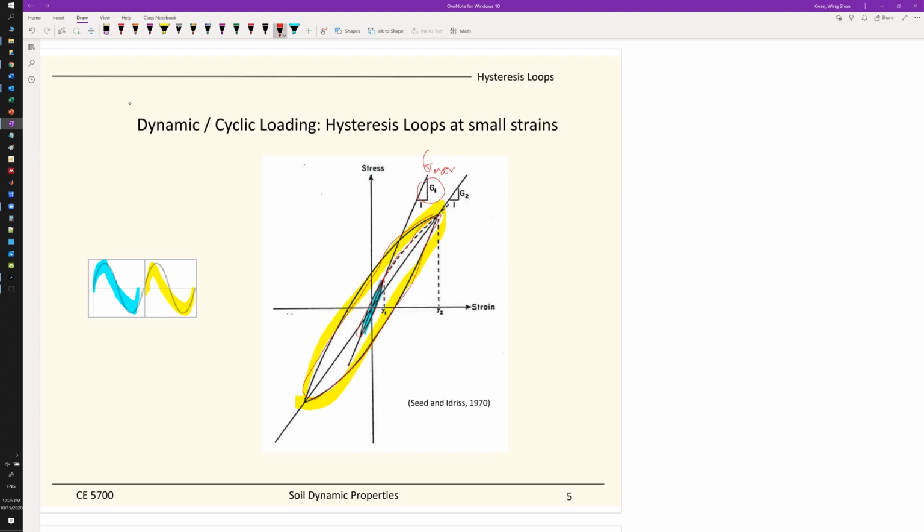And the subsequent hysteresis loop here, if you connect the two points, again the origin and the maximum point here, then you get the shear modulus, and this is another point with a corresponding strain level. So again, if we think about it in time history, time versus shear stress going through a soil element, this is the representation of the stress strain curve. So this is your set.